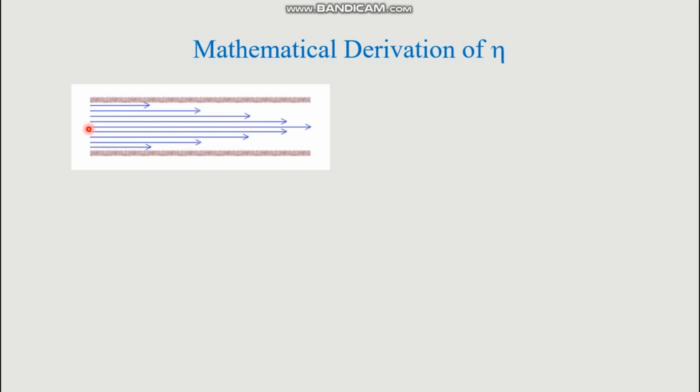This is the center of the cylindrical pipe, and along the perpendicular line of the cross-section of the pipe, the velocity of the liquid is highest, because the liquid molecules during their movement have to overcome the intermolecular attraction forces. This plays the role of the dragging force, which is known as the viscosity of the liquid.